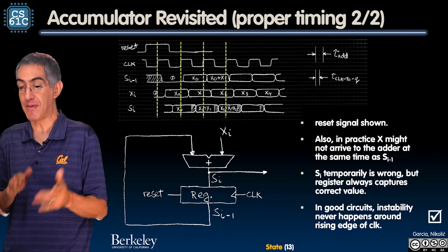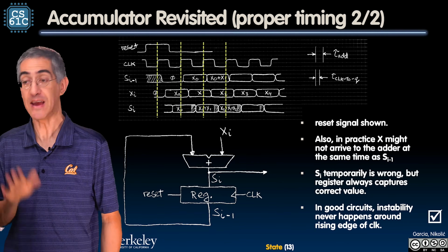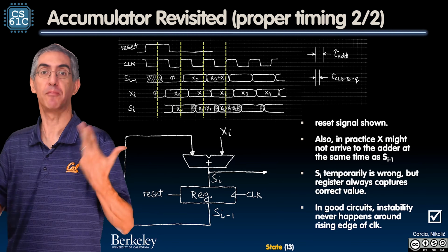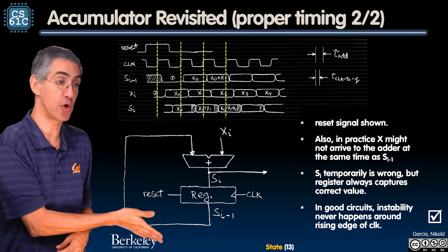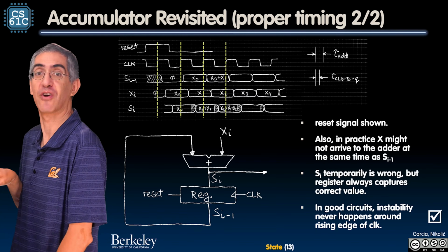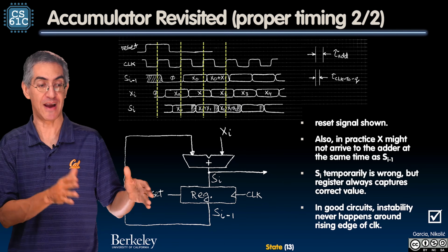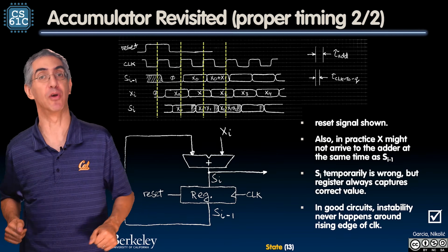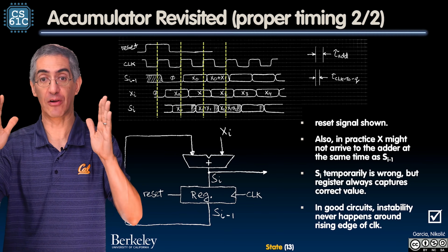I may have a value of a half, whatever that means for the voltages there. I may wobble. I may go up and down. Who knows? I may start ignoring my input and just hold this forever. Who knows how the flip-flop is going to break? That starts to happen if you ever have a changing value between setup and hold. And that's what starts to happen as I turn this clock frequency up and these yellow lines get closer.